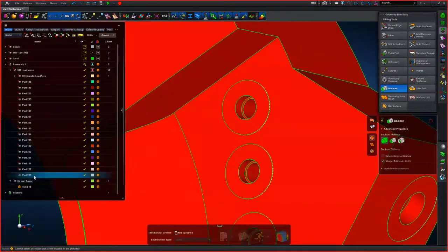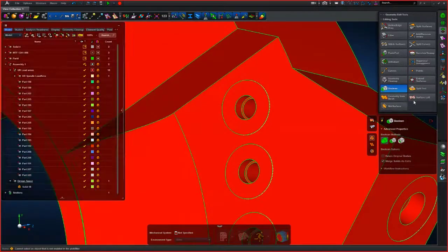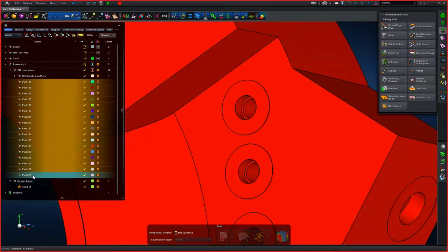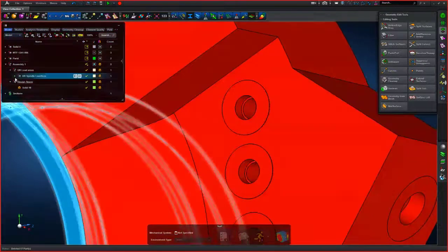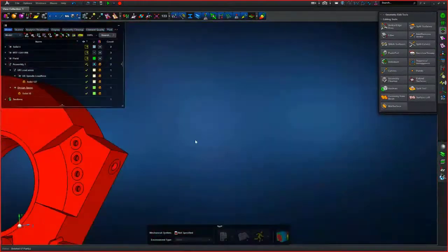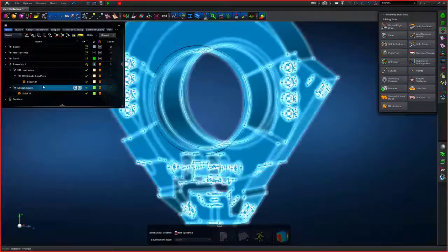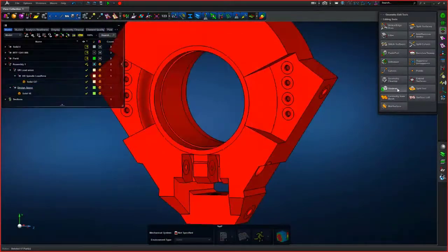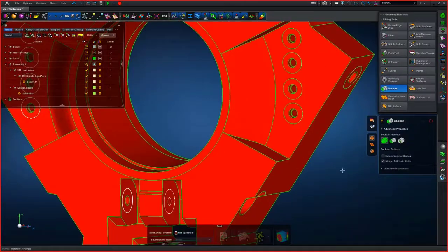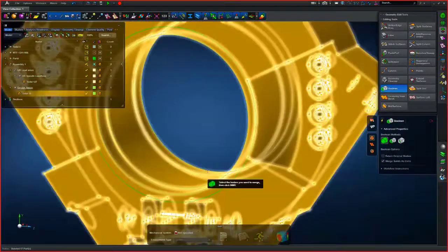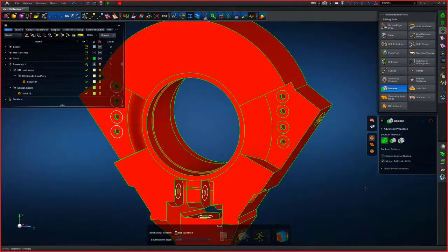So I'm going to delete these empty parts just to get rid of them in the model tree, to show this more clearly. And it took me quite a while to figure out why these two didn't boolean, because this inside bearing frame was quite important for me as a load transfer location as well.